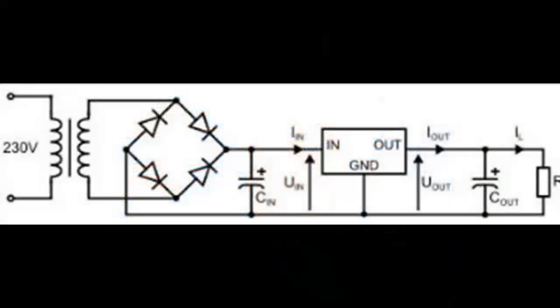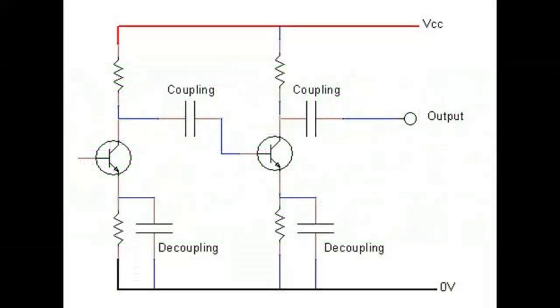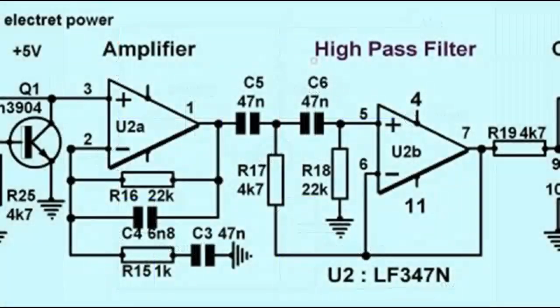Electrolytic or tantalum capacitors are placed across DC supply lines to filter away any AC content. Smaller capacitors, such as ceramic types, are also placed across a DC path to filter or decouple any RF voltages and signals. These are also used to connect between other components, such as transistors, to allow the signal to pass but block any DC content. There are many more uses for capacitors, and again, look up technical publications for more information.